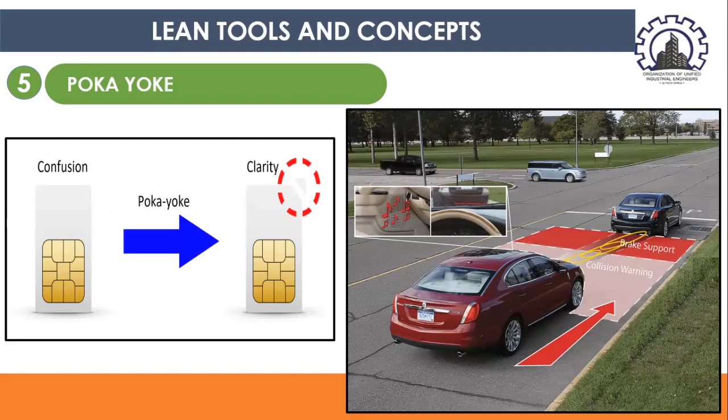Because there is no indication as to where you're going to be tearing that certain paper where the SIM card is inserted. So in order to apply Poka-yoke, you have there clarity, meaning to say you indicated a slight portion in the upper right corner of the paper in which the SIM card is being inserted. And so it will be very easy for you to tear it.